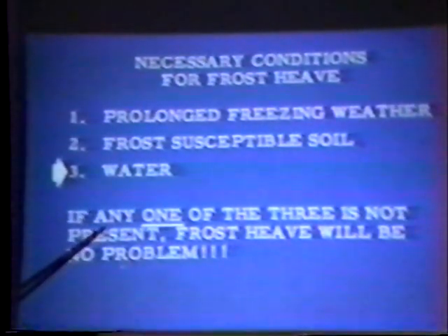But if we can get rid of any one of these three, frost heave will be no problem. If we can get rid of the water, if we can get rid of the frost-susceptible soil, there isn't much we can do about the weather, but we can work on those two. And of the two, the one that I think we can do the most with easily is to get the water off the surface of the road.